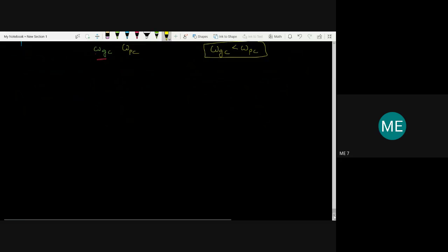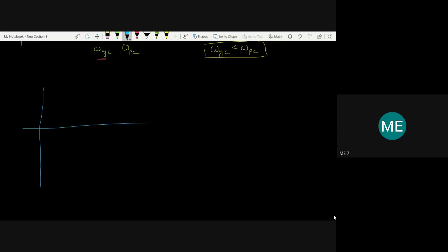Similarly, we can look at when the system is unstable. After plotting the Bode plot, this is 0 dB, say 20, 40, 60, and minus 20, and we can also draw the phase angle here. Say I have a minus 180-degree line like this, and the phase angle and magnitude plot are like this.